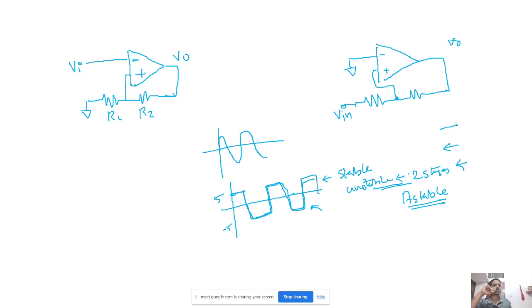For example, if it was at plus 5 volt, at some trigger or disturbance which we created manually, it will suddenly go to the unstable condition, and after a while it will go back again to stable. So it won't be affected later. This is monostable, that is, it has only one stable case, and the other is the unstable condition. And for bistable, always it is stable.